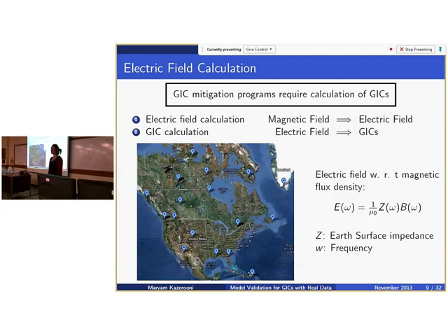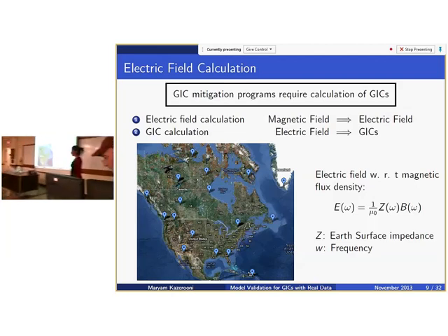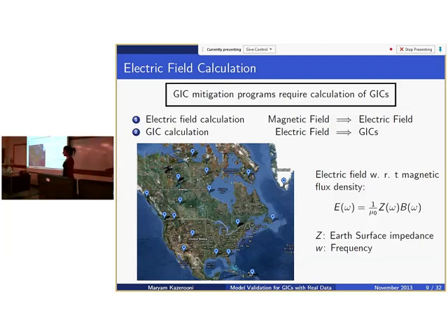Is that something they do now to keep some sort of headroom on the transformers and additional capacity, just in case? Is it something they do in practice, to keep a transformer from being fully loaded, kind of like reserves? Reactive power is not necessarily a question of how heavily loaded it is. The reactive power losses on the transformer don't depend on the loading of the transformer. They depend on the GICs in the transformer. But yes, if you derated your transformers, you could do that.